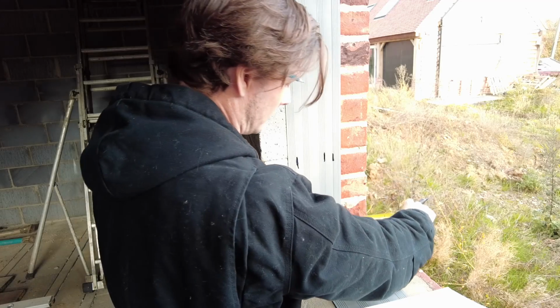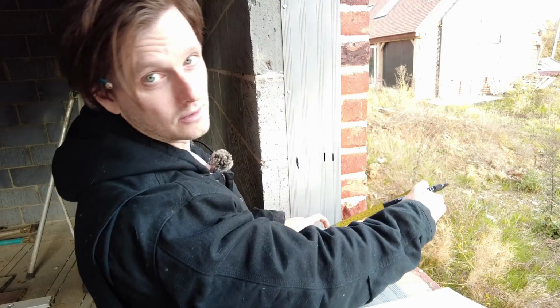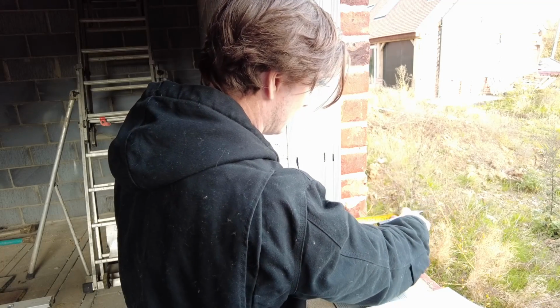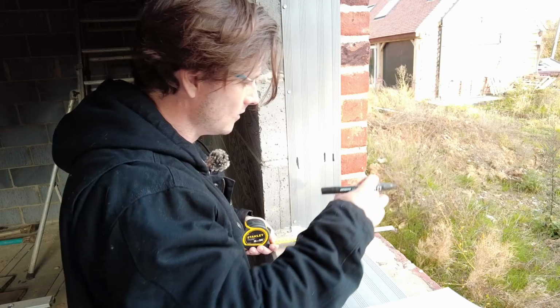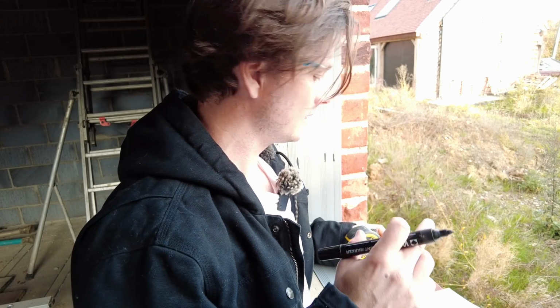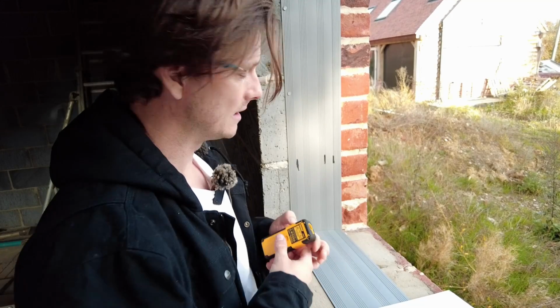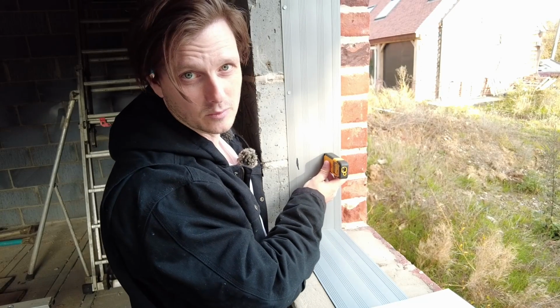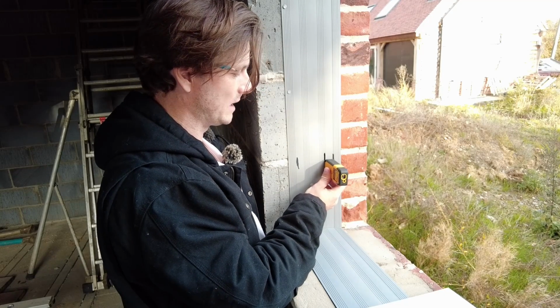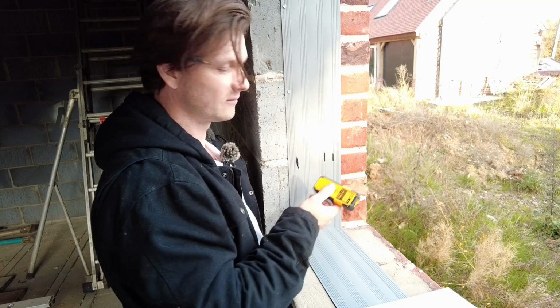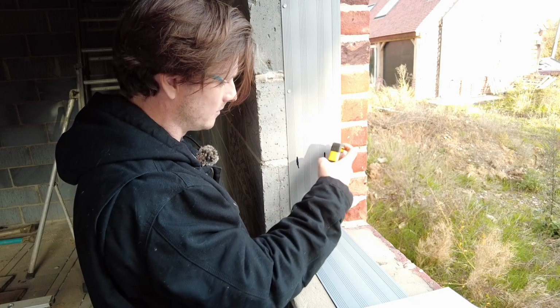So you need to make sure obviously your sill is going to come out and extend beyond the brickwork. Your projection off of the front of the facework, you really want about 40 mil minimum. That would be ideal. Remember, if you have render or anything like that, you need to make sure that you're going to bump it out further. And whilst I'm here, that's where I'll take the measurement from, exactly where the back of the window is going to sit. And that's why you put your cavity closers on first, because that squeezes it in a little bit more.